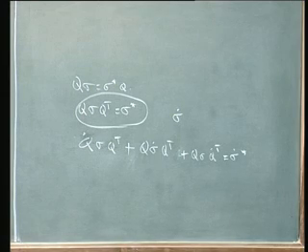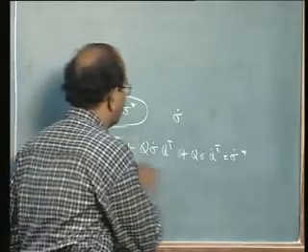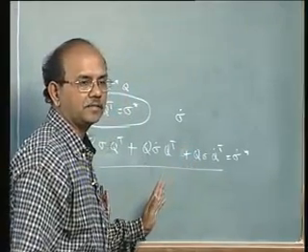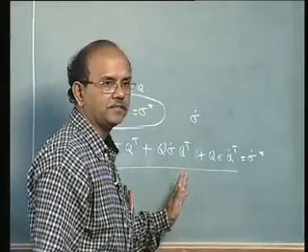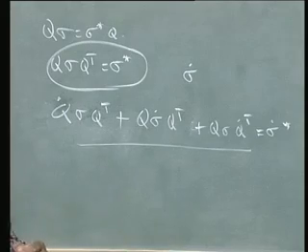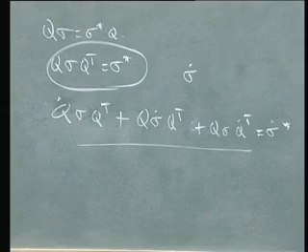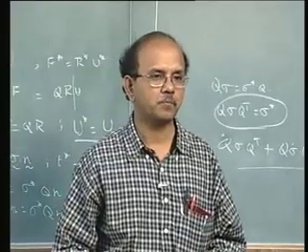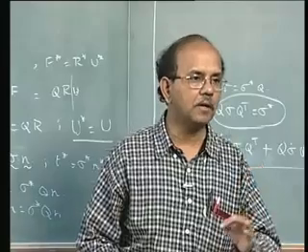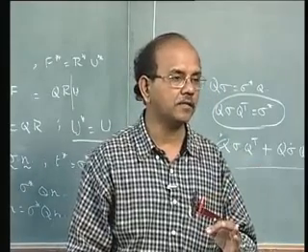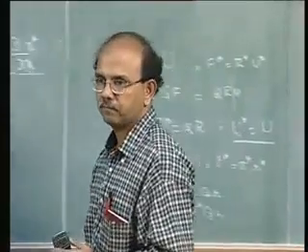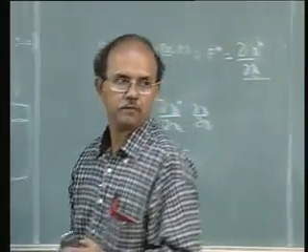So obviously this equation tells us that because Q is a function of time, sigma dot is not an objective quantity, and we have to do something else in order to make sure that it is an objective quantity. So sigma dot cannot be used in the constitutive equations. Is that clear?